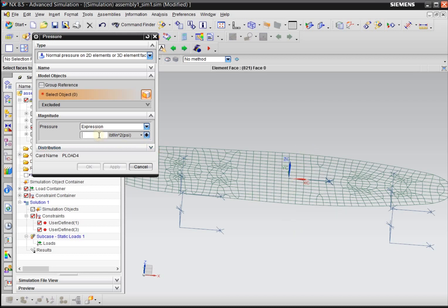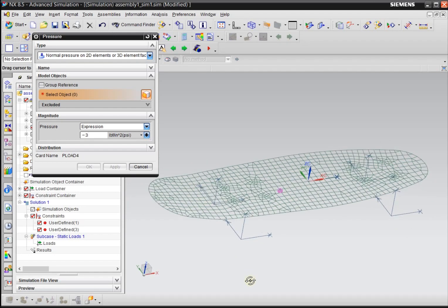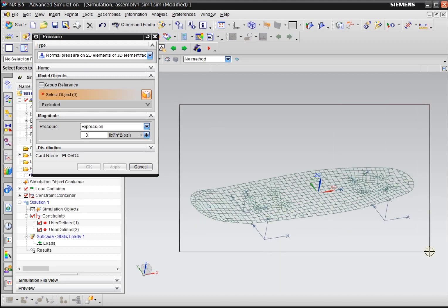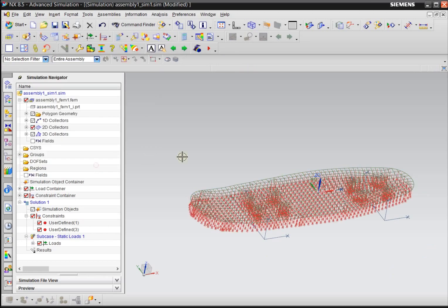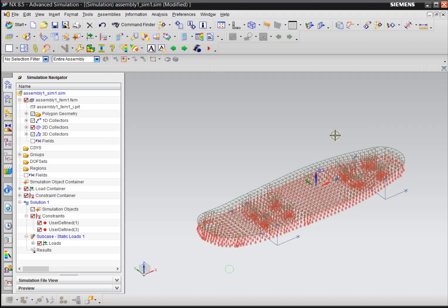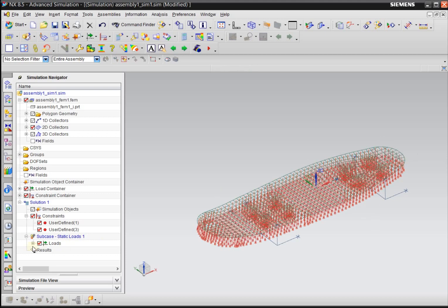So that's going to be negative, and the number is going to be 3 pounds for a uniform pressure. But I think Dr. Zada has done that in class, and for uniform it's pretty easy. You just select the whole board, then you click OK. This will give you a uniform 3-pound pressure. If you multiply by the area, that's about 300 pounds. That's a pretty big guy.